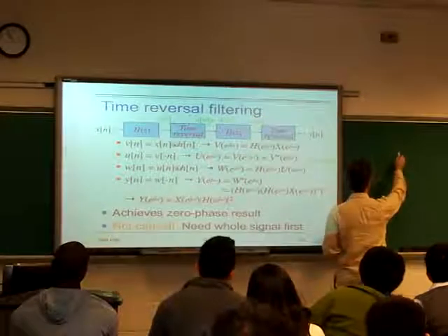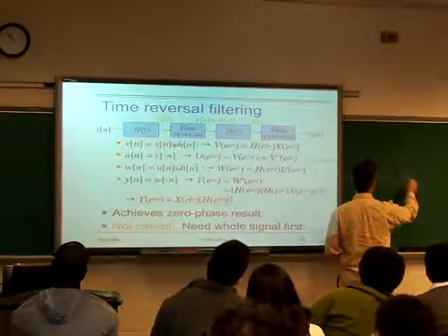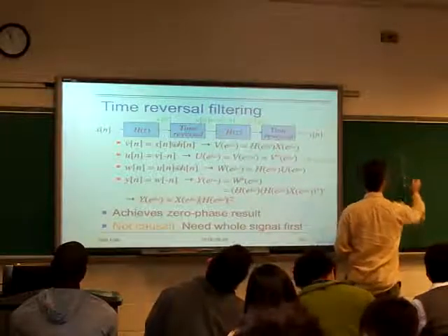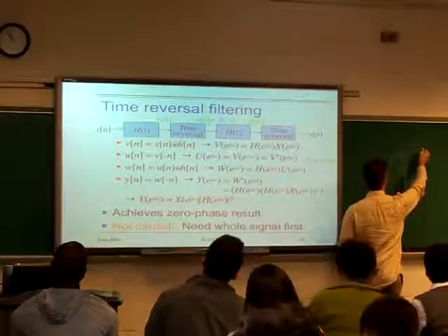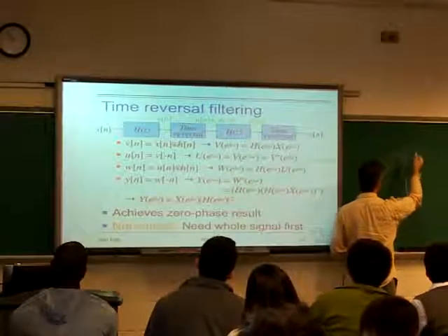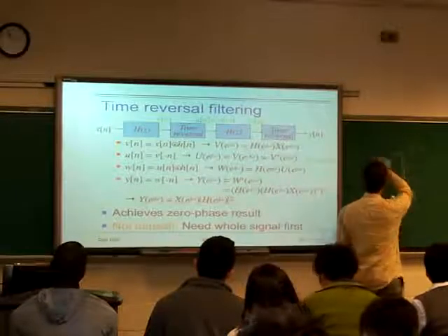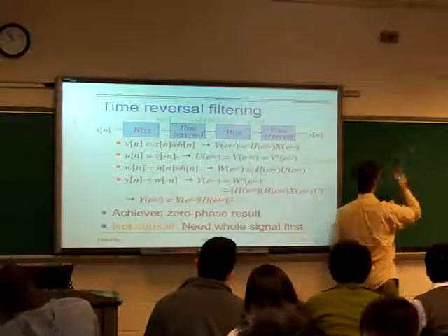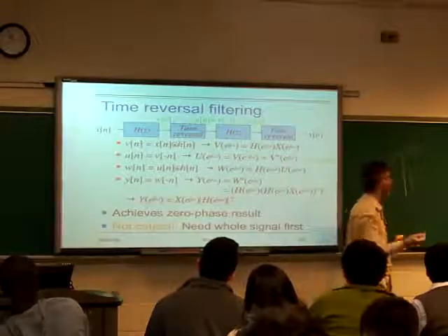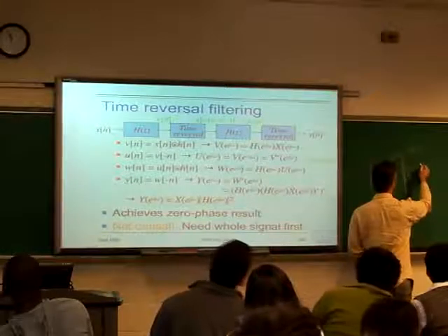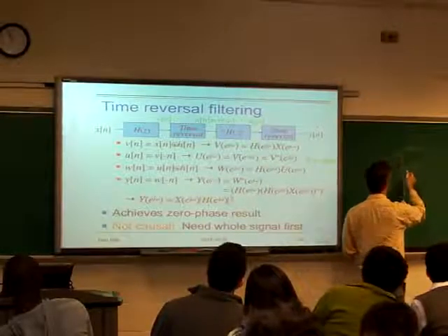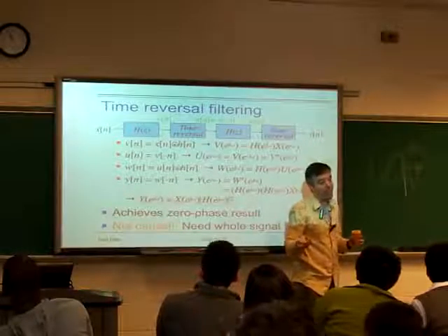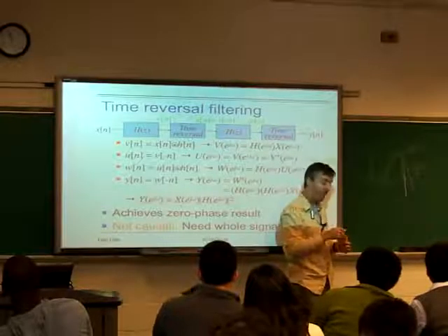So now we just want to design a filter that looks like this, where if this is some function H of omega, say, a magnitude response, and I'm now plotting the dB response as Q of omega, then what I actually want is a system where it's Q of omega over 2. So if this is now 0, say, then that looks like the same kind of problem. It's just a slightly shallower filter that I'm trying to design.